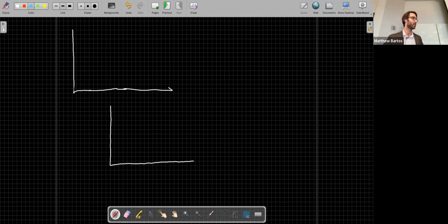And our ultimate hydrograph is built like this: we take this impulse here, we know its response because it's an impulsive rain event, and so we end up with some component of the hydrograph here.